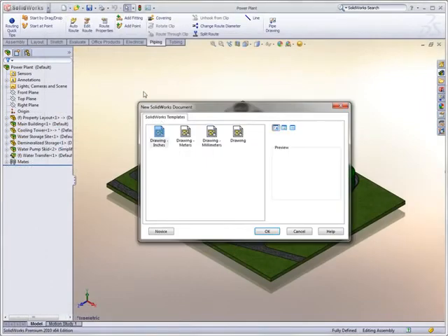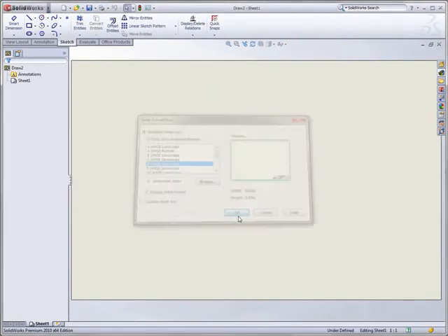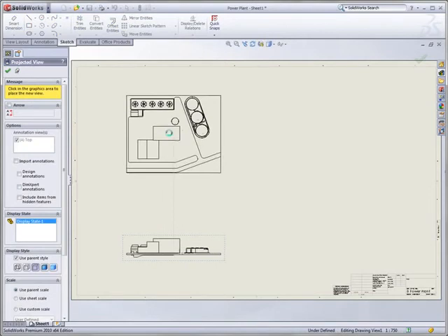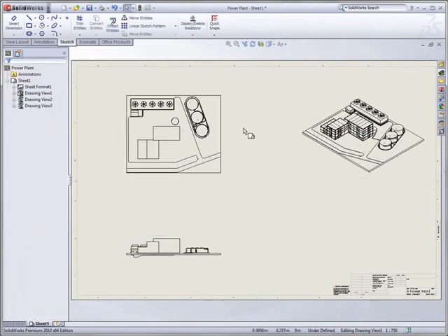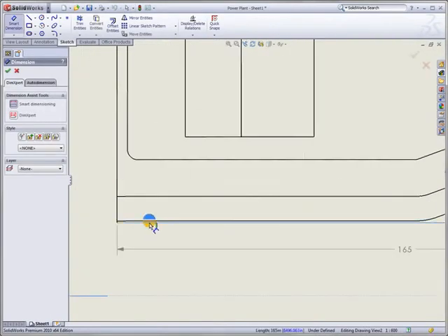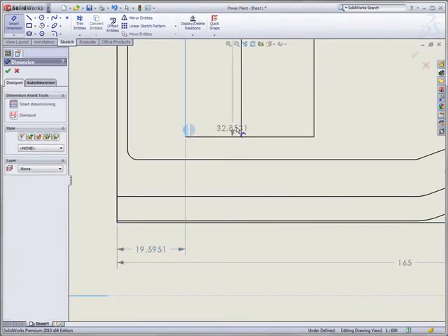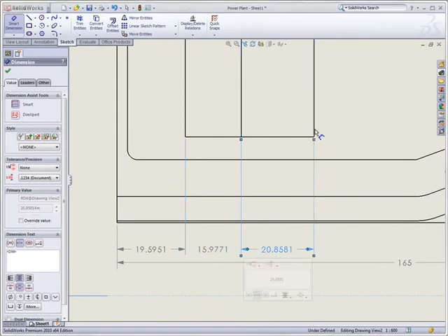Assembly drawings or general arrangement drawings are just as easy to create with SOLIDWORKS. Simply drag and drop the desired elevation or plane views onto the drawing, and SOLIDWORKS creates the views utilizing the 3D data. Detailing these views is easy with SOLIDWORKS ultra-fast dimensioning tools. With SOLIDWORKS, dimensions automatically space and locate themselves based on other dimensions and available space on the drawing.